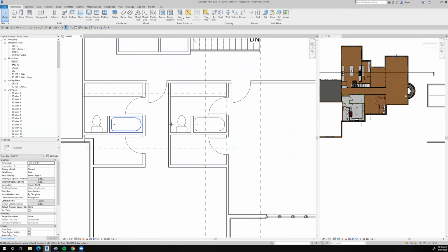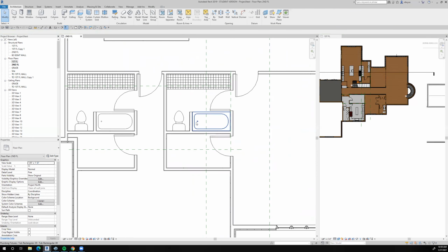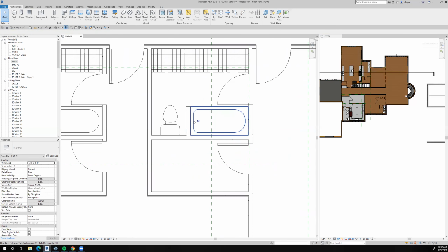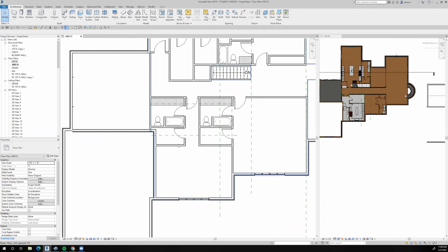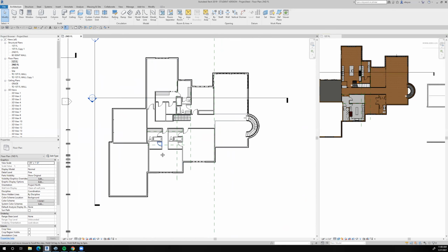Now here, that's probably a good place for the access panel. Plumber won't like it because he or she will have to work around the toilet, but at least that's a better place to have that access panel. It's just a removable panel on the wall that allows us to access the plumbing components, because over time there are things that'll need to be changed, that'll wear out, washers or some part of the faucet might need replacement or repair. So I could put the access panel on this wall, but then you would see it in what I consider to be the finished space. It's a better spot over there. That's just the concept there.